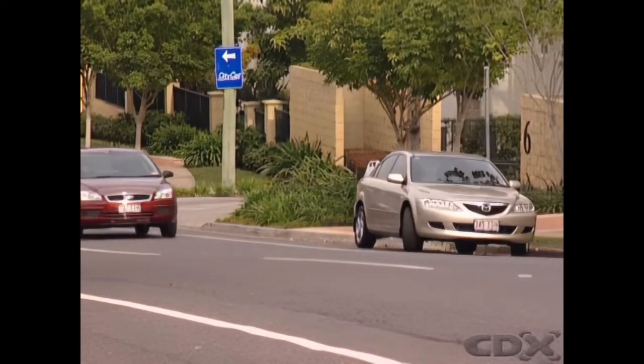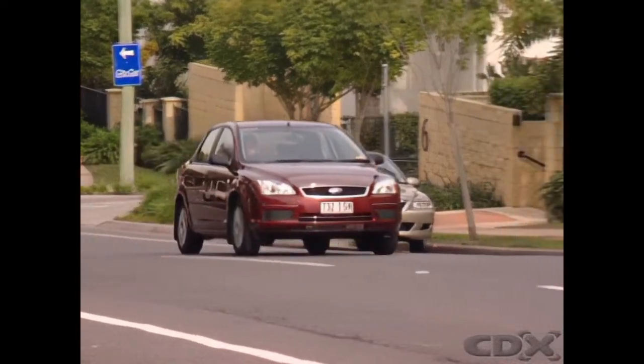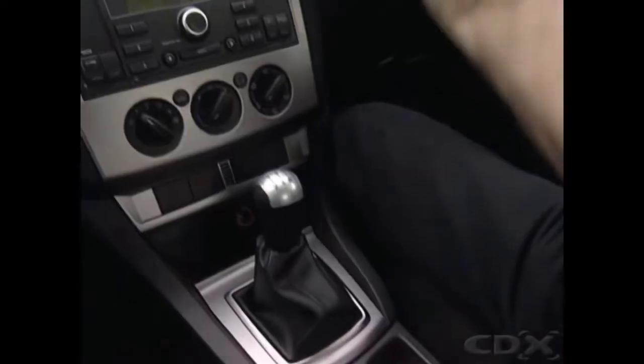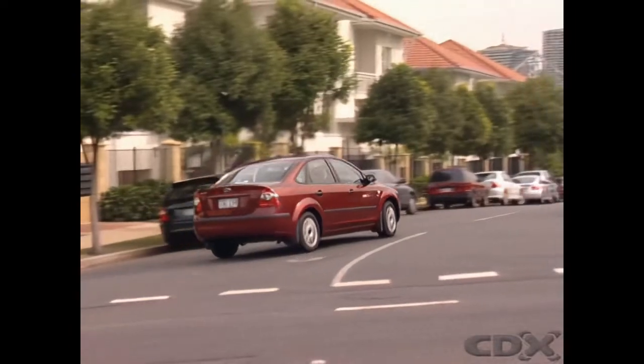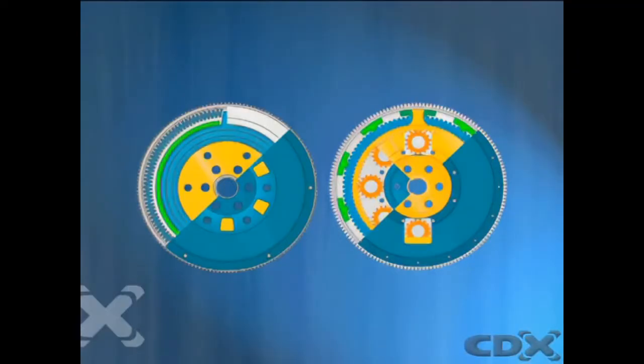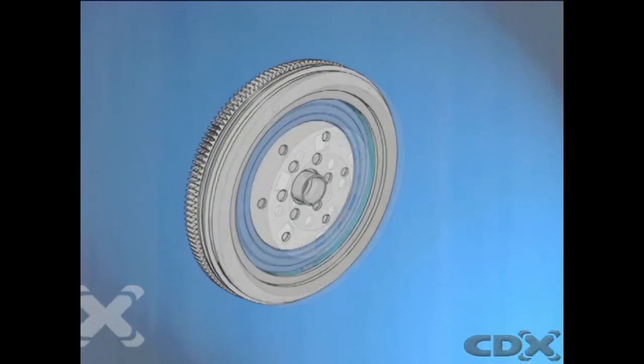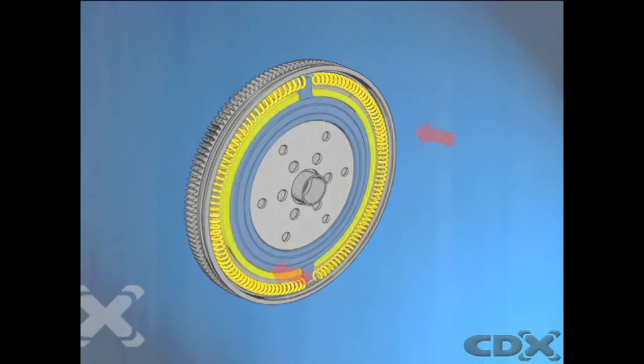The dual mass flywheel, or DMF, eliminates excessive transmission gear rattle, reduces gear change shift effort, and increases fuel economy. There are two basic types of dual mass flywheels. The first is made up of a primary and secondary flywheel with a series of torsion springs and cushions.